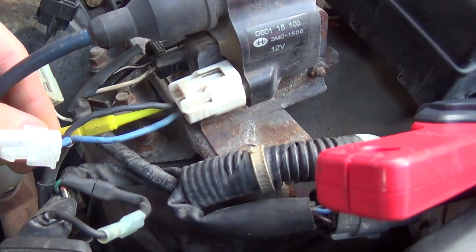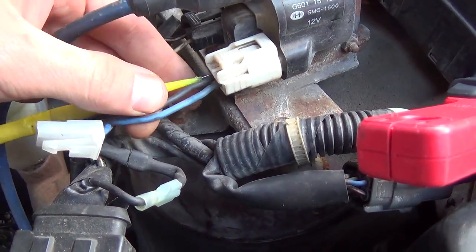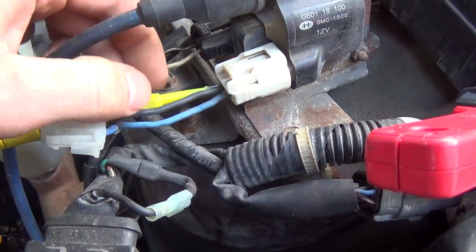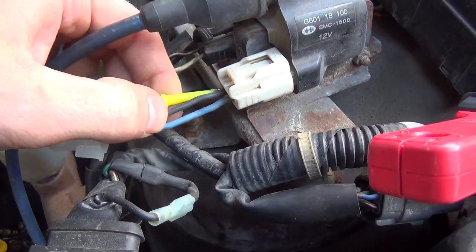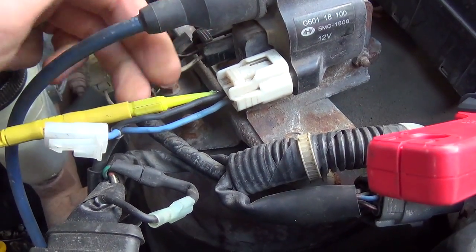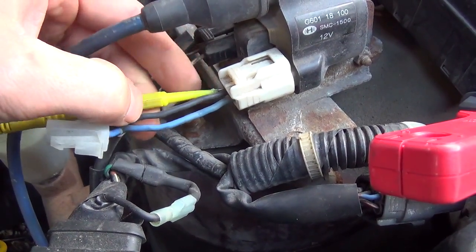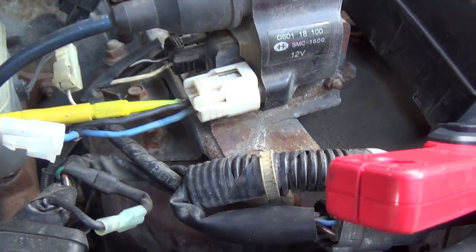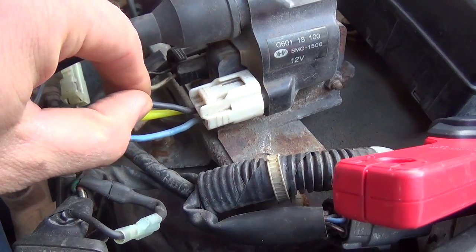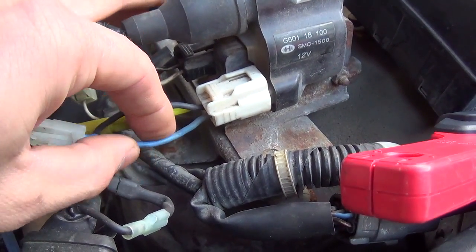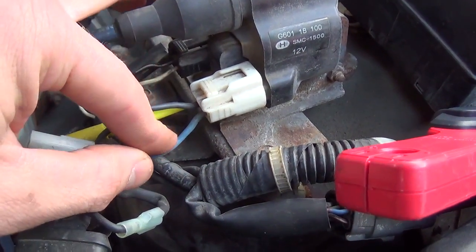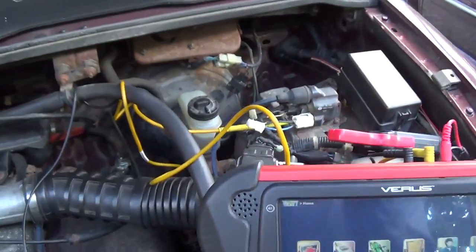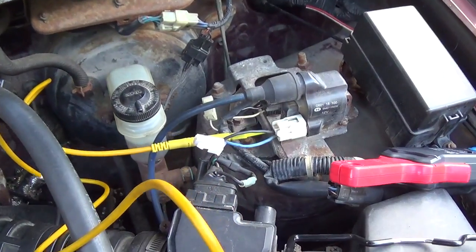So in this case, the 2 wires that we're interested in are the ones that go to the ICM. So first, since we're interested in power consumption, we're going to measure the voltage drop and current flow at the same time on each wire separately. First we'll do the one that powers up the logic, the board, and then we'll do the one that is actually the primary coil current. So we're going to do 2 channels simultaneously.